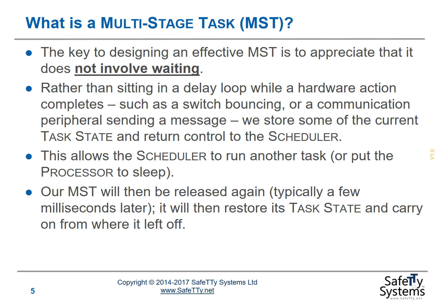If we do it this way, for example, if our task runs every 10 milliseconds, we do some initial activity, we return from the task, we call the task again 10 milliseconds later. In that 10 millisecond gap, some other hardware or other external activities may have taken place, and we then respond to the changes in the overall system state.